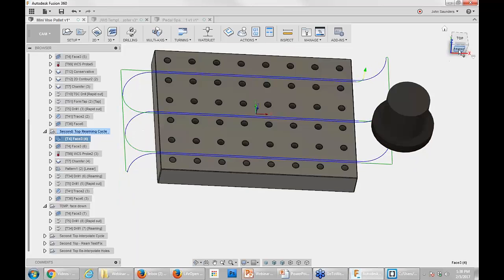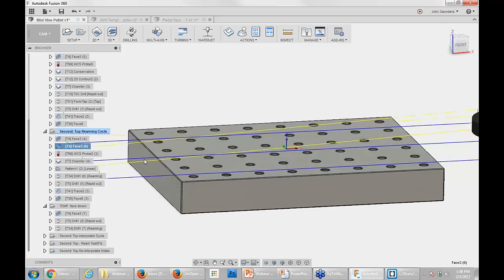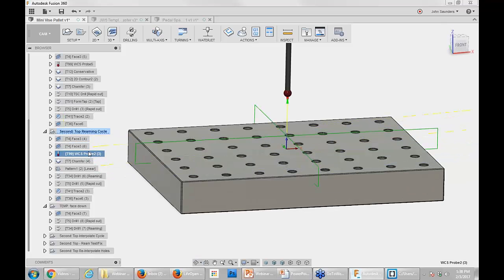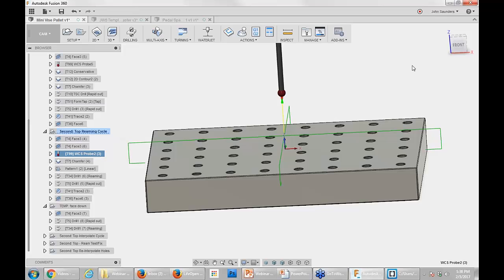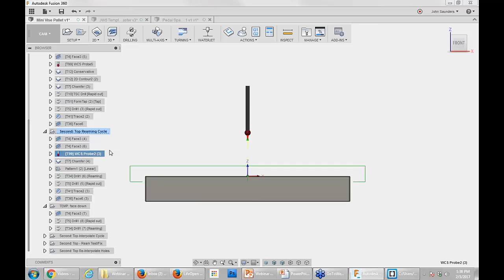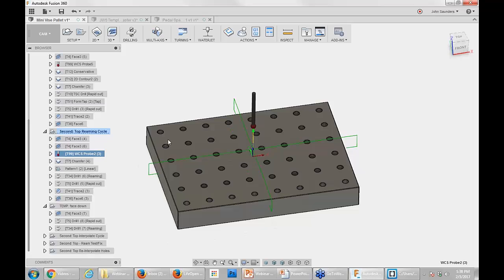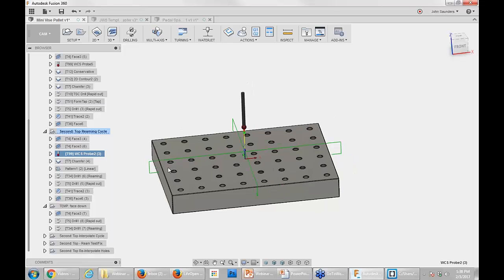So after that mushroom cap has been decked off, I've now exposed my final part, and that's what I want to probe. So this, I think, is really the great example of where I will probably always keep midstream probing. And sure, there are ways that you could secure the part with a stop and then pull the stop away, but I'll tell you, it's just such a confidence booster to me to know when we're trying to hold on some of these dimensions inside of a thou, I find that a Renishaw is better than a hard stop that I have to then remove, because at some point I want to walk all the way around the part.